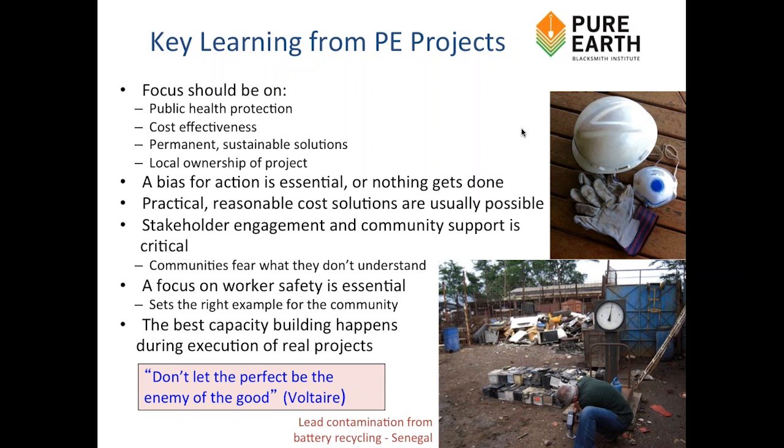That's actually a very good question. Workers should have their blood tested. The people that we hire to do the lead remediation work, the blood testing before and after, if feasible, you have to take into consideration, are there the appropriate laboratories and equipment nearby, or do you want to use the local field kits for blood testing?